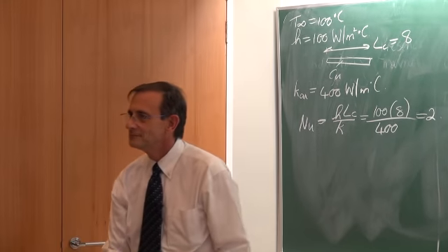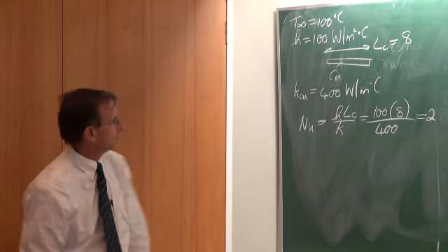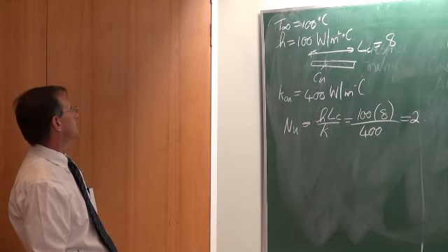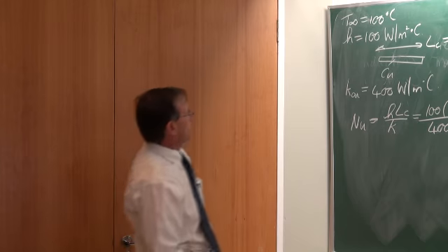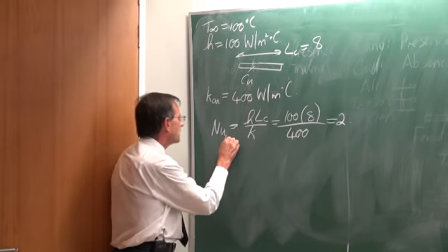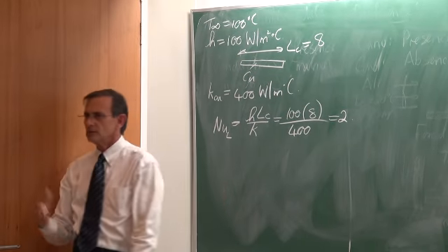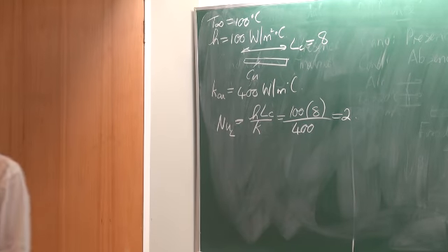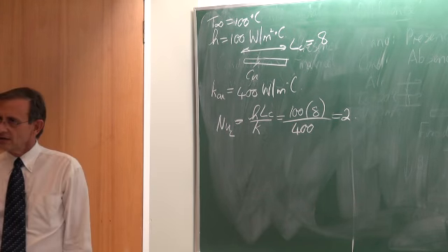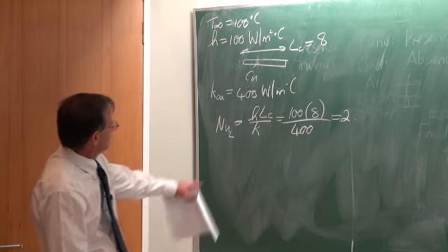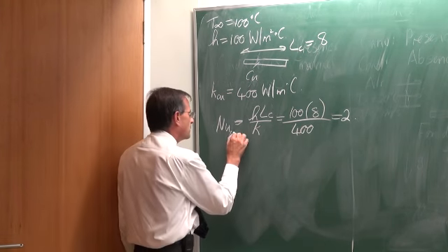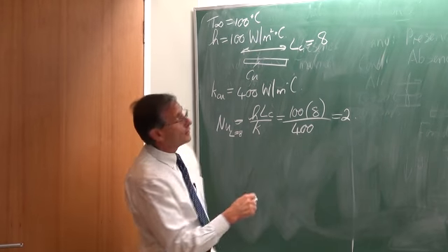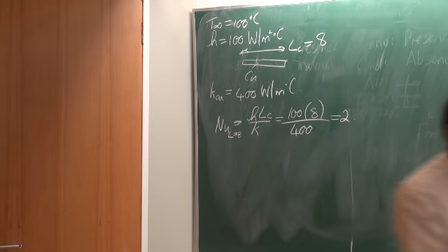Why? Because that's not the characteristic length that you used. It's not just the length of the plate, it's volume divided by area. Well, no, I can say the Nusselt number based on the length of 8 meters. So as long as I do that, that's fine. Yes, if I say a Nusselt number, I should say on what length it has been based, and in this case, the length of 8 meters.